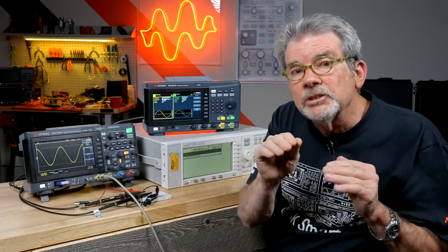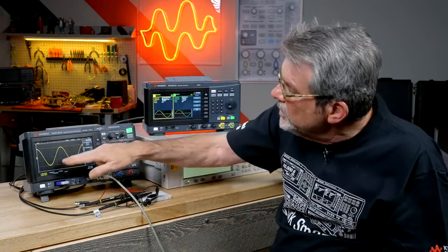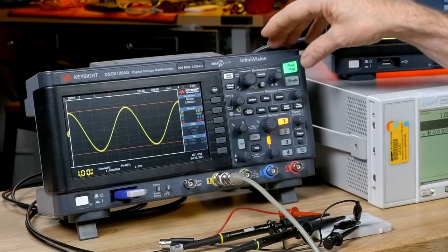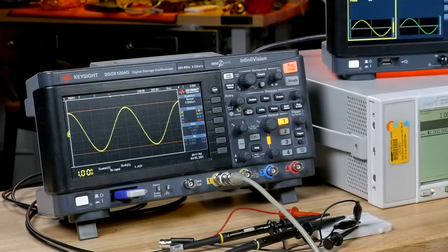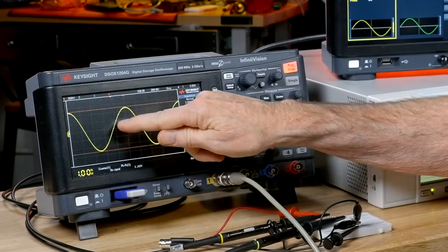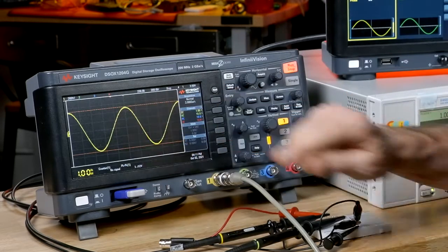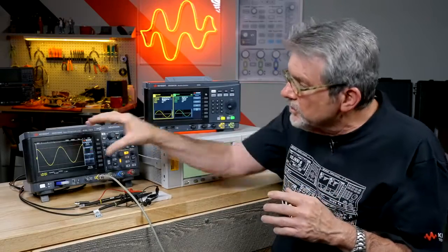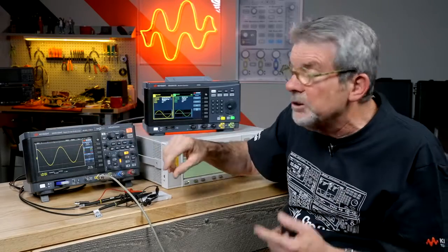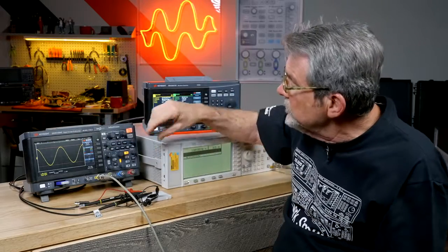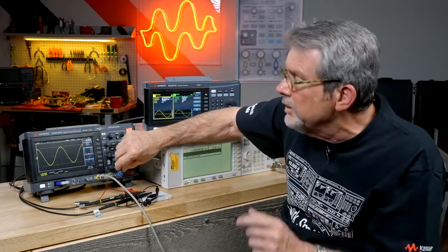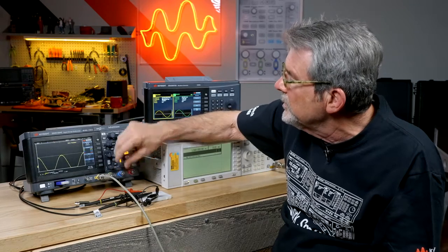Can you see those levels? Currently, it looks like a continuous waveform. If I do a single shot acquisition, we can see things jumping. If you look real close, you can see things jumping up and down a little bit. But the only way to really see the discrete levels of even an 8-bit converter is, now that we have it stored, I'm going to zoom in on the stored waveform.